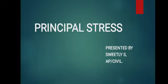Today, we are going to study about the principal stresses. In order to know about the principal stresses, first we have to know what is meant by principal plane. The plane which has no shear stress is known as principal plane. If any plane has no shear stress, then it is known as a principal plane. Therefore, in this principal plane, only normal stresses are present.